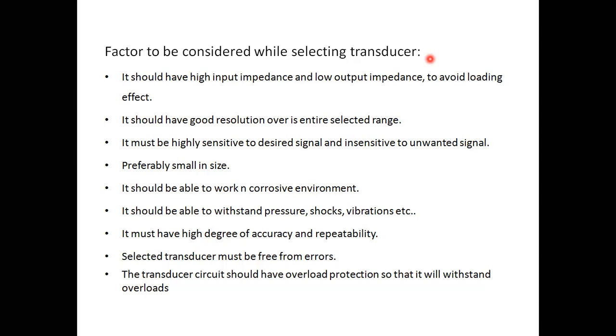Okay, so what happens if I use an RTD or thermocouple made of copper leads? Then these copper leads will corrode in an oxygen environment. If I use iron, it will rust. So I should not have such properties or such problems. Okay, so environmental capability must be there for the instrument. And the instrument should be able to withstand high pressure, high shocks, high vibrations, etc. So these are the characteristics which you have to look after while selecting a proper transducer for a particular measurement.